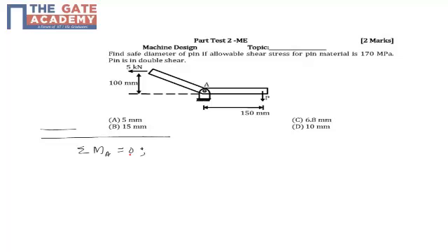If you want to draw a complete 3D free body diagram, you have to put the unknown reactions at AX and AY, and P is also unknown. Then the three equations, sigma Fx, sigma Fy, and moment about A, have to be solved in order to get the unknown reactions AX, AY, and P. We do this problem in a slightly different way.